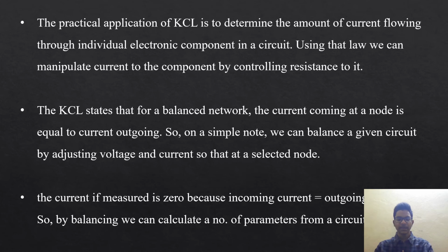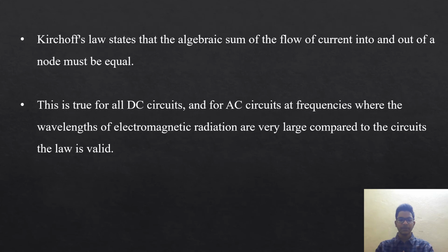The potential application of KCL is to determine the amount of current flowing through an individual electronic component in the circuit. Using that law, we can manipulate current to the component by controlling resistance to it. Kirchhoff's law states that the algebraic sum of flow of current into and out of a node must be equal.